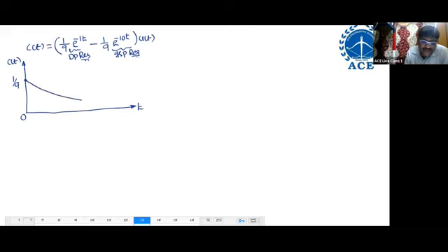That means it exponentially decays and reaches the steady state by 5 tau. What is the tau here? 1 second. And for the other, what is the tau? 0.1 second. Reach the steady state by 5 tau. Tau is 1 second, that means 5 seconds. This is the dominant pole response.